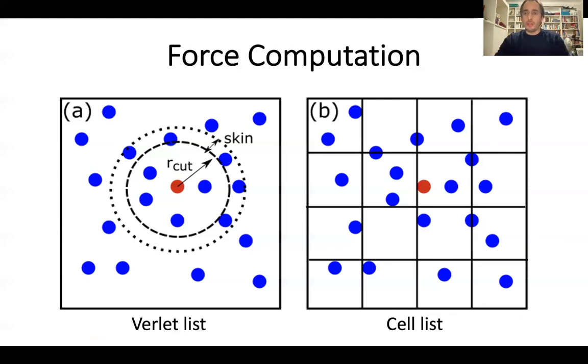If you decrease the size of this cell list, you'll have fewer failures on testing the particles, but you have to check first, second and third neighbors, which will take a longer time. So this is also a trade-off. What LAMMPS uses by default is to consider the size of the cells as half of R-cut, and this is just an optimization.